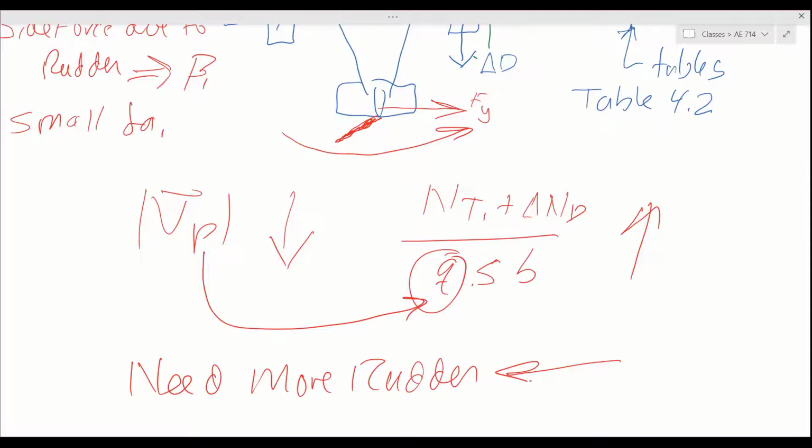So in fact, this sets up a situation where at low speeds, you need to be able to calculate how much rudder you have and whether you have enough rudder to counteract the yawing moment. And that's why the King Air that crashed out at Mid-Continent or Eisenhower, it took off, so it was going at low speed.